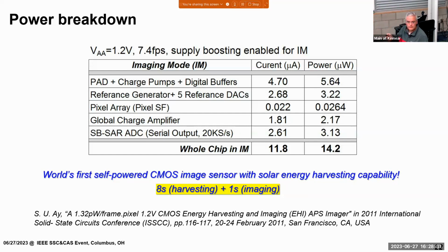Sullivan, University of Michigan, they have a paper, they provide like 2 microwatt, but they don't include the pad power. So as a result, they only report this one, and maybe this one. They end up with very, very low power. And then you think that, oh, they have a 1 microwatt image sensor running at 30 frames per second.